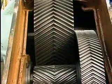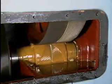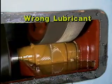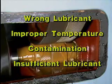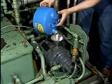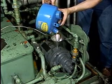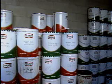Problems with lubrication or lubrication systems can soon lead to problems in a gear set. The basic causes of lubrication problems for gears include using the wrong lubricant, improper temperature, contamination, and insufficient lubricant. One type of gear lubrication problem can occur when the wrong kind of oil or grease is added to a gearbox during routine maintenance. The improper oil for a particular gearbox may not have the proper viscosity or oil additives to handle the loads, speed conditions, or temperatures that the gear set operates under.